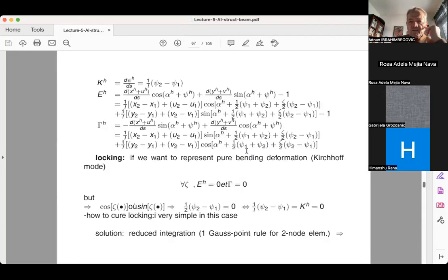and rotation psi. So if I go through these developments, then I can build my exact expression for the bending strain, axial strain, and shear strain. You can see this one is linear, but these are heavily nonlinear because cosine and sine are, of course, nonlinear functions of psi. Now, this is a little bit less obvious when you look at such a long expression.